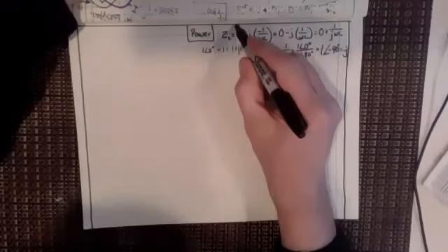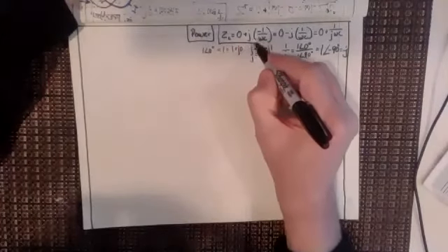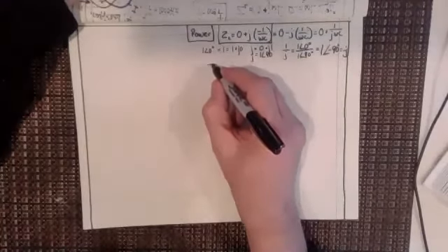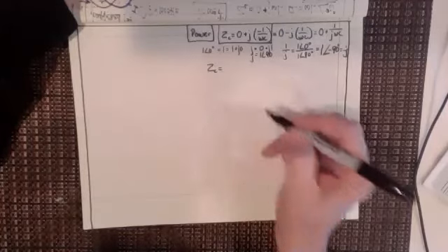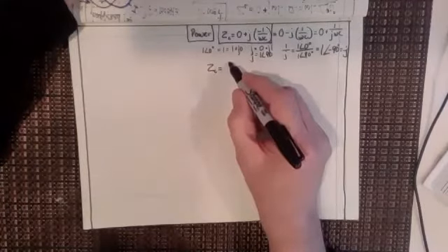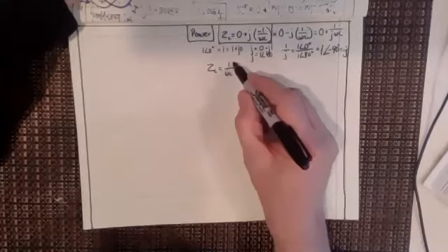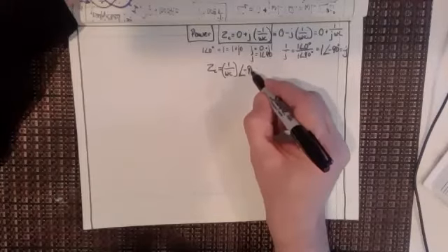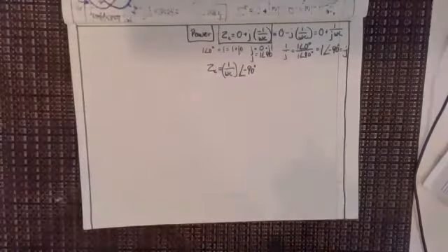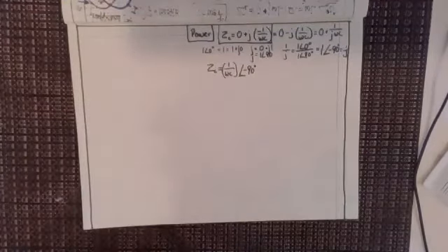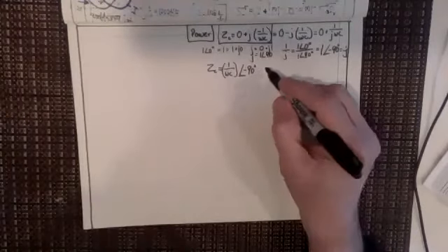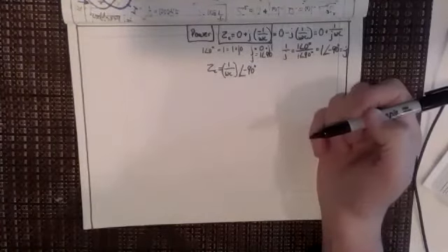And this is the way that I like to teach the capacitance of that. And the way that you would write that as a phasor is 1 over omega C, right? That's the magnitude, at an angle of minus 90 degrees. And we can use minus 90 degrees here because we're just adding and subtracting angles all the time when we're doing this. We're not doing anything like taking square roots of complex numbers in their phasor form, so don't worry about that. All right, so that's what we've got, and that's the capacitance of thing.